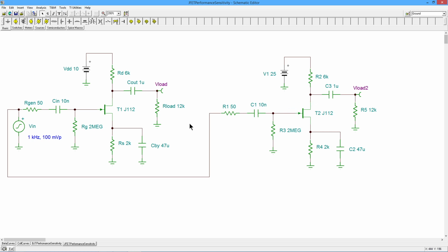If you go back and look at the lag network capacitances, I do kind of make a deal about making sure you get a decent value for your C drain gate or your C gate source, same thing on the bipolars, because it will have an impact. And we can see it right here, right? So remember, a model is a model. A model is not reality. A model is an approximation of reality.